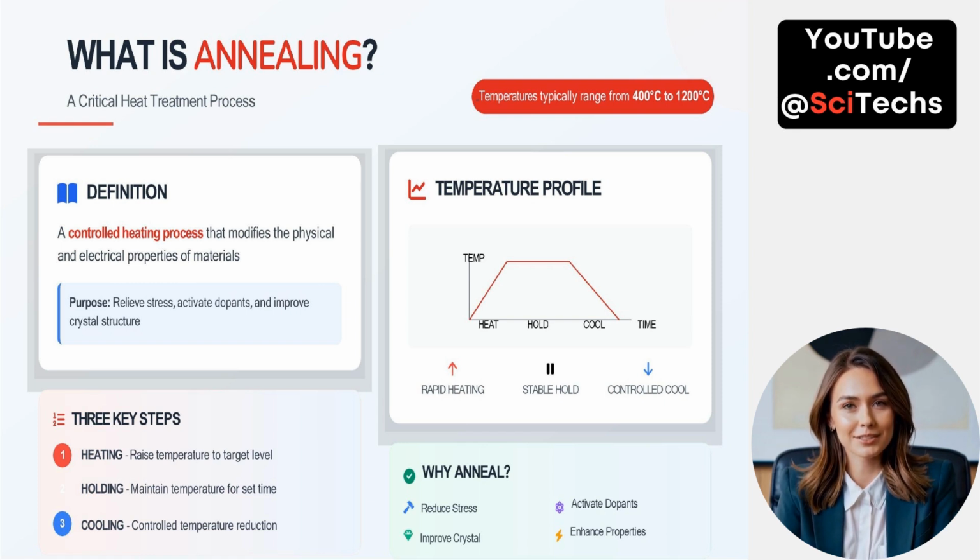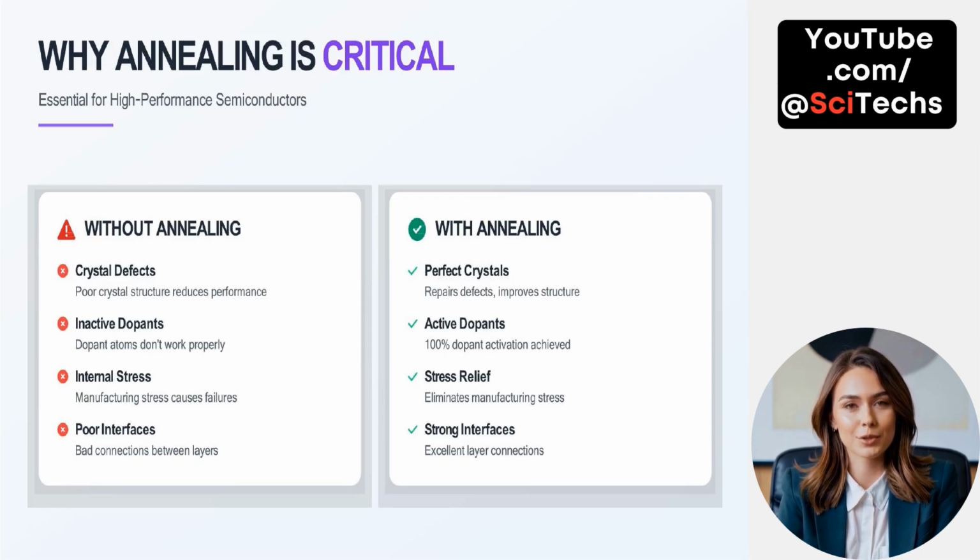First, heating raises the temperature rapidly to the target level. Second, holding maintains that temperature for a precise duration to allow reactions to occur. Finally, controlled cooling gradually reduces the temperature to avoid thermal shock or defects. The temperature profile follows a distinct pattern of rapid rise, stable hold, and a carefully managed cool down. Annealing is critical because it reduces stress, enhances material properties, activates dopants, and improves the crystalline structure necessary for optimal electronic performance.